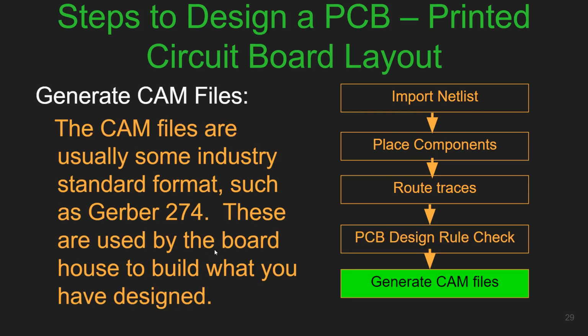Now, CAM files are the last step. Once you generate the CAM files, you will use them if you are using the milling method. You can use them in the CNC machine and you can mill your PCB. And if you're using the etching process, then you can take the printout of those CAM files.